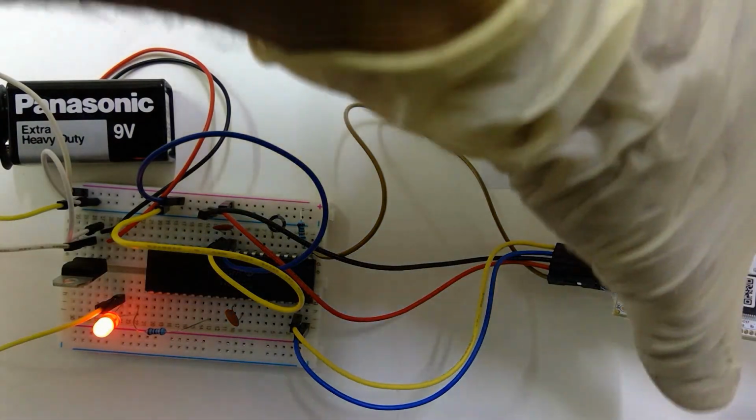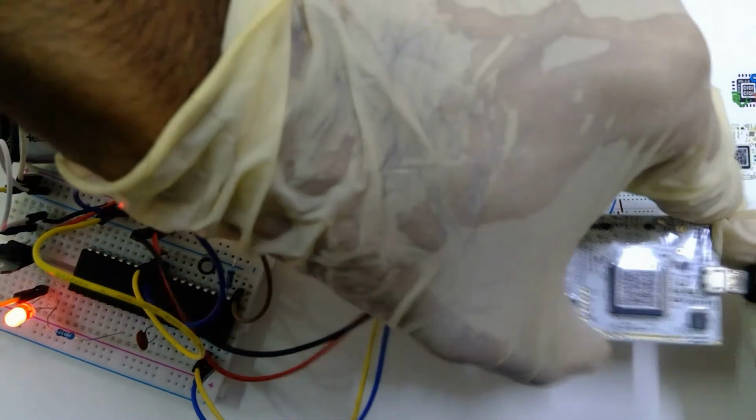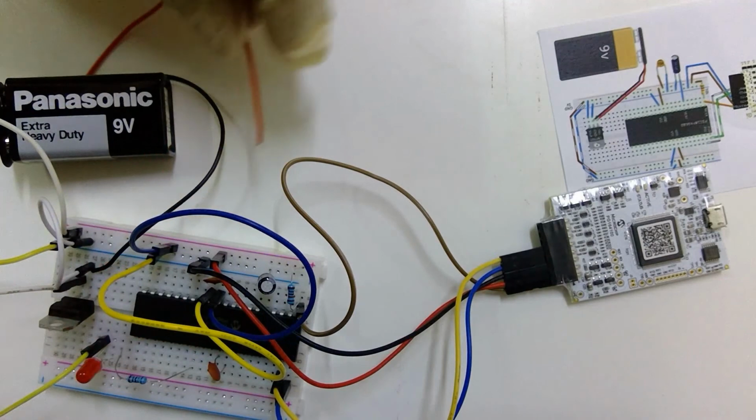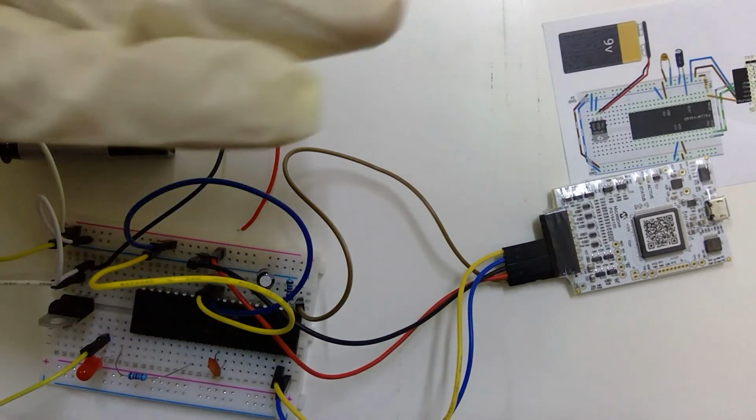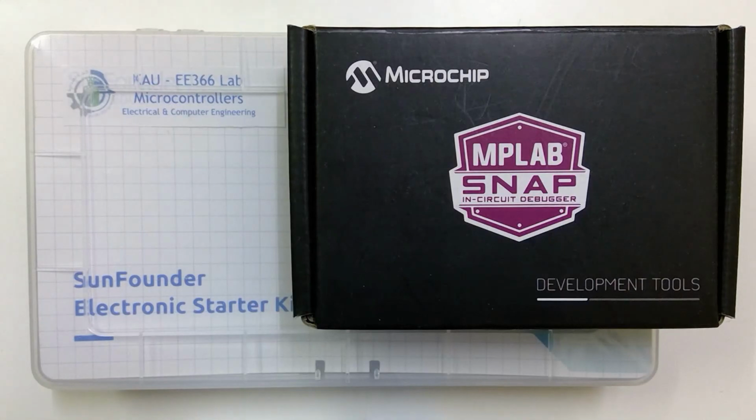After completing this tutorial, disconnect everything. Disconnect the MPLAB Snap, disconnect the battery first to save power, and disconnect all the components and keep them back in the kit. So that is all for this tutorial. Practice using MPLAB Snap to download the hex file to the microcontroller, and we'll be using this MPLAB Snap in the upcoming lab activities.